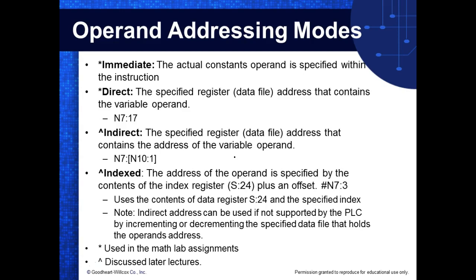This is how your instructions address those operands. So the two we're going to predominantly use, starting off with, is immediate addressing. What's immediate addressing? This is the numbers inside the instruction. So those counters, when you preset the register, you put 1000 in there, that was immediate addressing. You understand that? The other addressing mode we're going to use is called direct addressing.